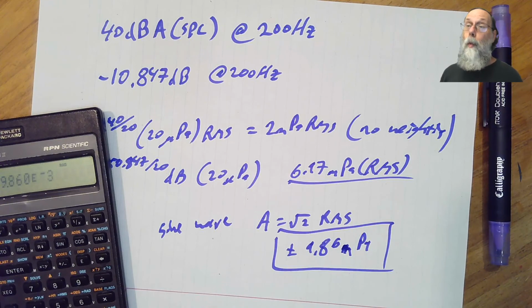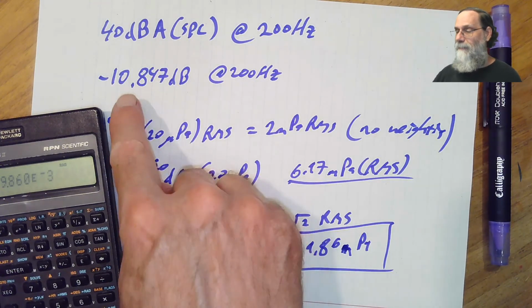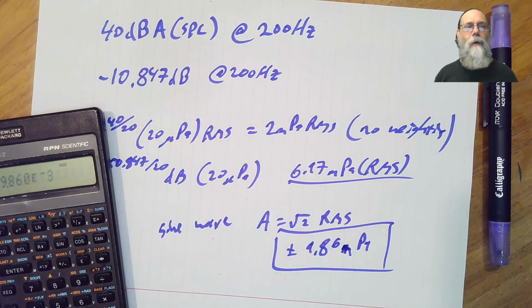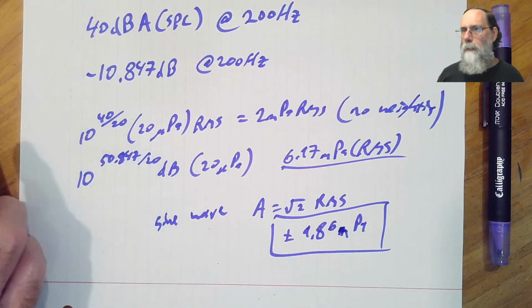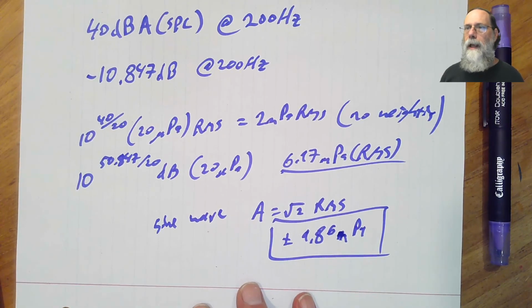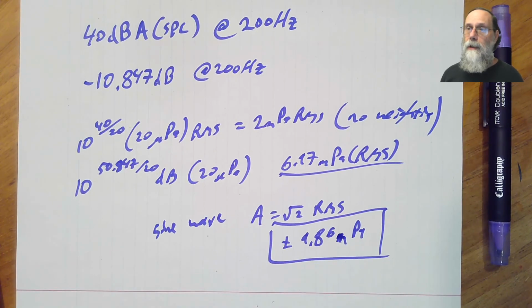Still obviously way, way smaller, even with this correction we've got, than what you would have from using a DC pressure sensor. Where you'll be using this sort of calculation is in figuring out how much signal I'm going to get from my microphone. Microphones are specified in terms of how many decibels of gain they have, usually negative because there's less coming out than going in.